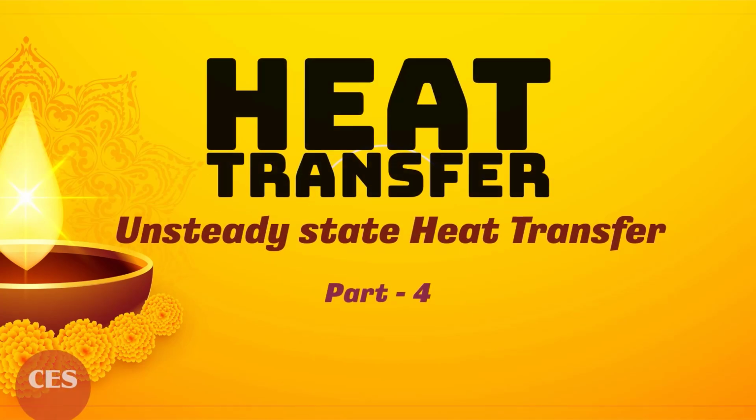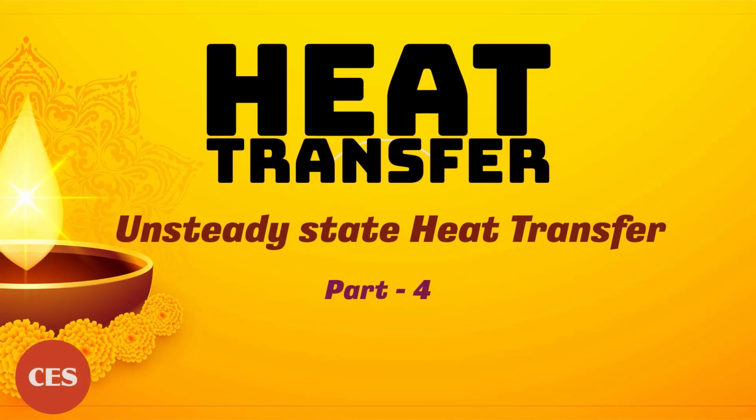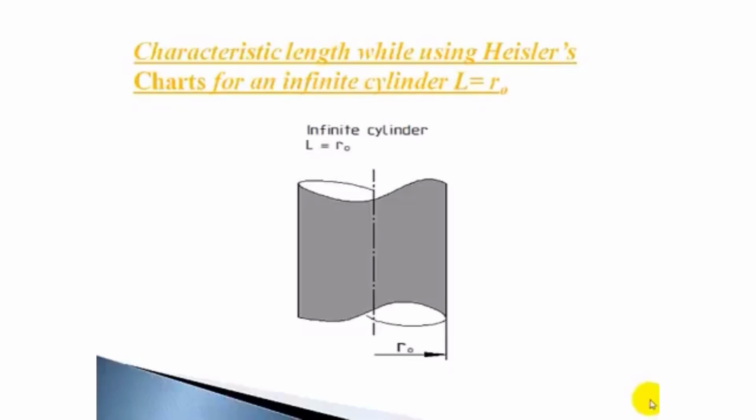Today we will continue our class on unsteady state heat transfer. In this class I will explain the usage of Heisler's chart for an infinite cylinder. As I mentioned in the previous class, while using Heisler's chart, the characteristic length for an infinite cylinder is taken as R0, where R0 is the outer radius of the cylinder.